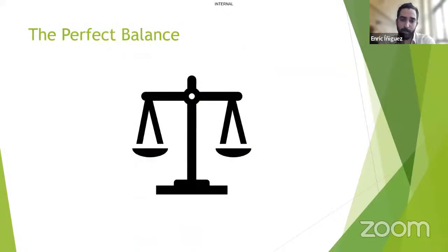That said, let's get a little bit into action. How can we optimize the design of a solar PV plant, reducing the LCOE as best as we can? Most of the decisions we take during the preliminary design phase can be represented by this simple image, a balance. We want to keep this perfect harmony between an efficient project in terms of energy production and an economically viable one, reducing the capital investment and the operational costs. Sometimes the proper balance is outside what we consider a good or optimal design. So how can we determine which is a good or a bad decision? Again, by comparing the LCOE of all the presented cases